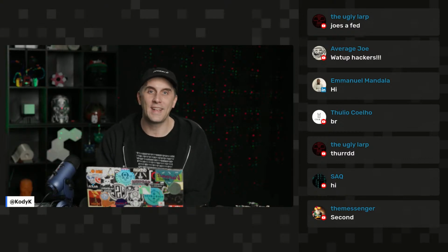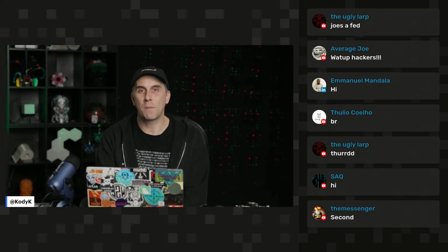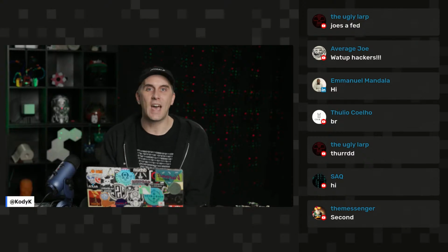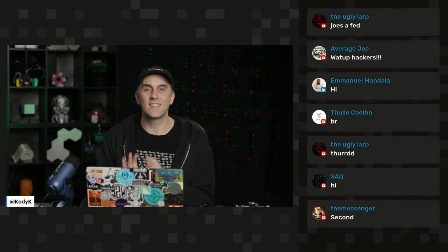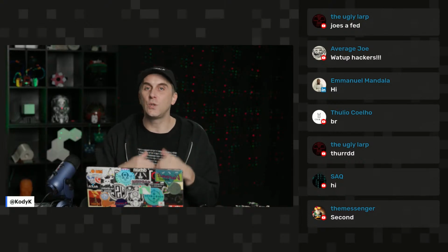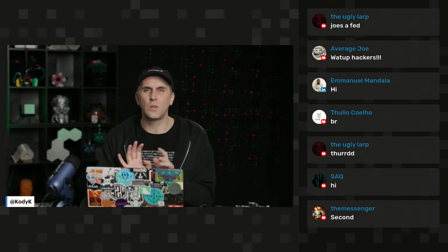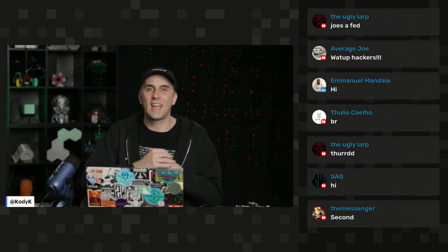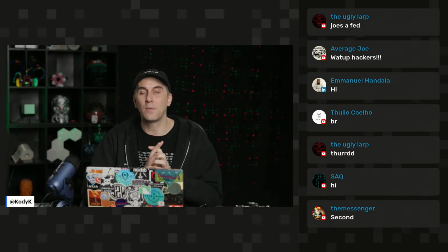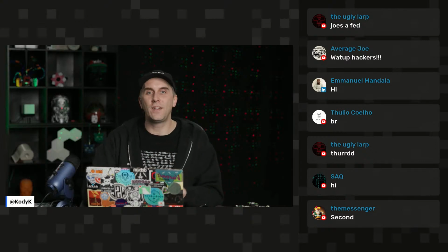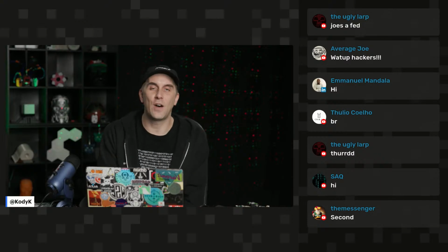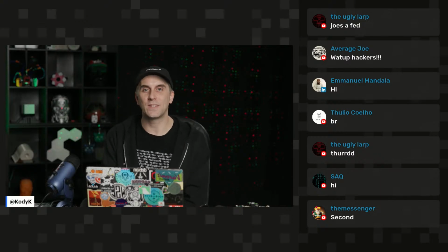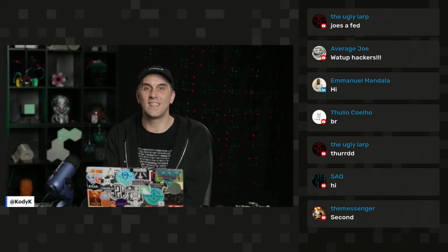The only problem is that everybody in Europe uses a different frequency. So I'm going to have to get a bunch of different chips than I would in the United States. The LoRa radios here use 915 megahertz. The ones there use 800-some megahertz, and they are not compatible, apparently. I will need different hardware. So to avoid committing numerous radio crimes in Europe, I'll need to make some purchases following this cool announcement that I was accepted. But yeah, again, this is really exciting.